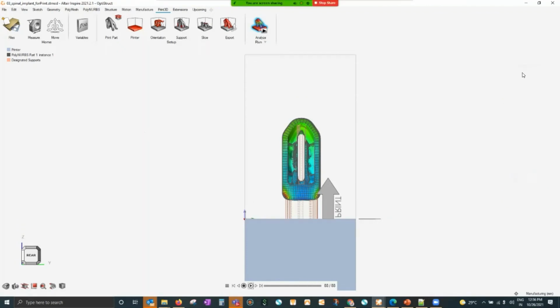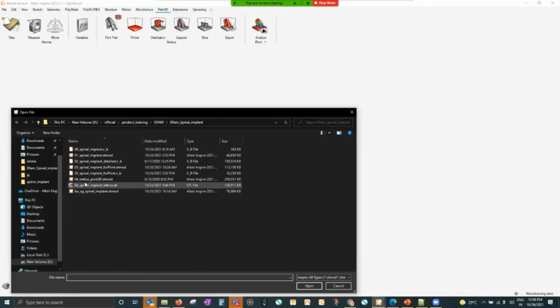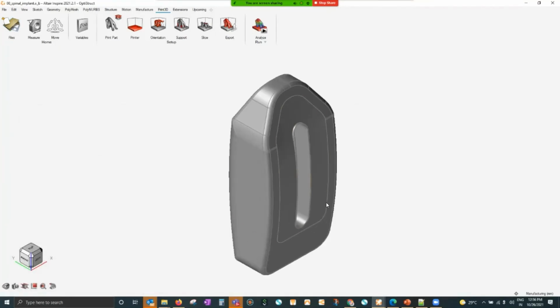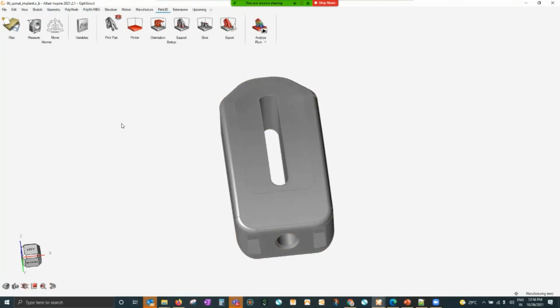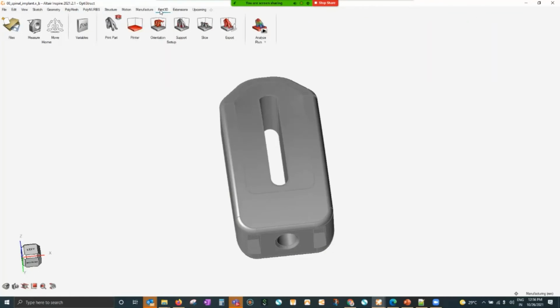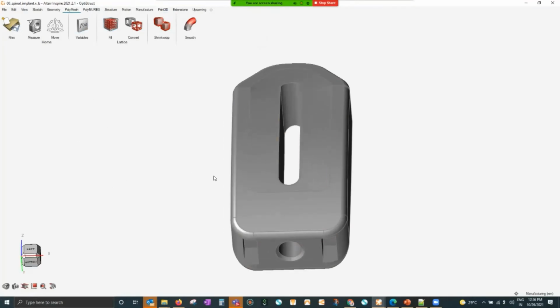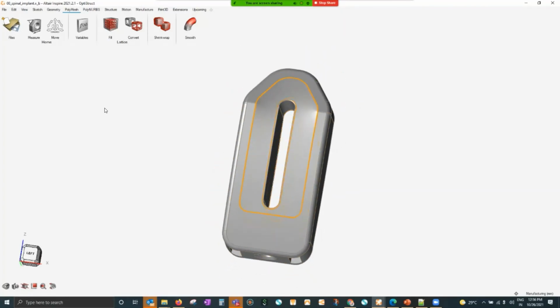So how to do that? Very simple. We'll start again, say, clean this model, and we'll start our first design, that is 00. We'll bring this model again. And once I bring this model, what you have to do is go to polymesh. Initially we were on structure, then on print 3D for the 3D printing process simulation. Next we'll go to the polymesh tab. In this polymesh, the aim over here is to convert this design space, which was earlier a design space, to lattice.